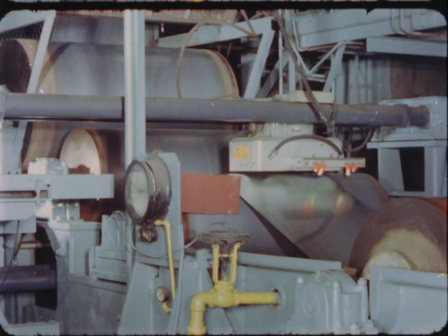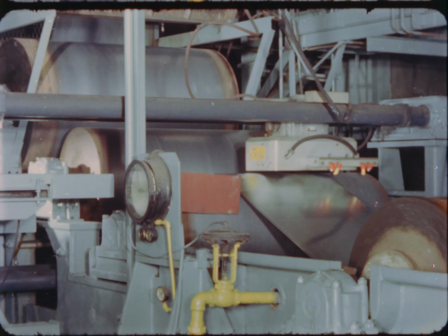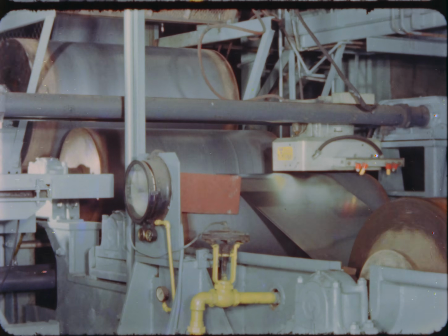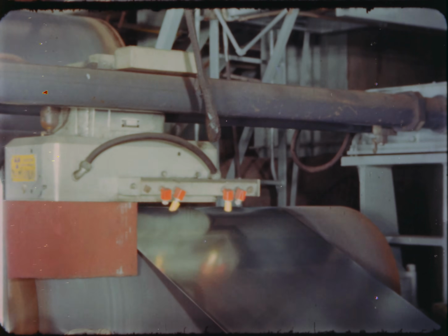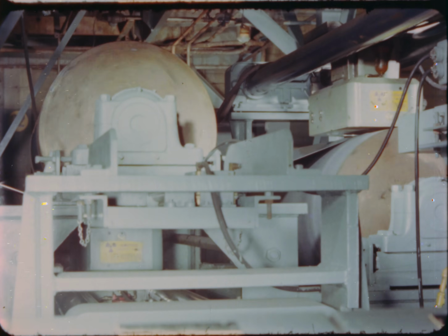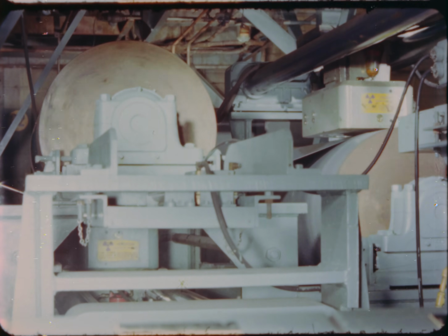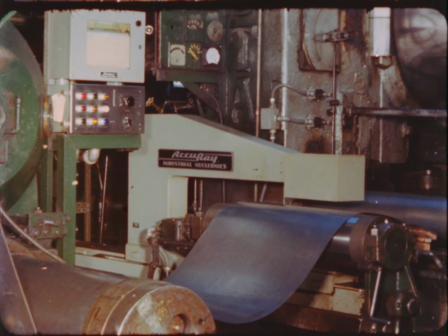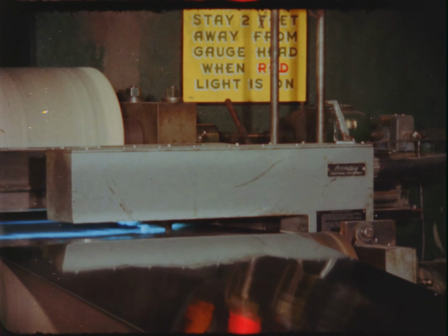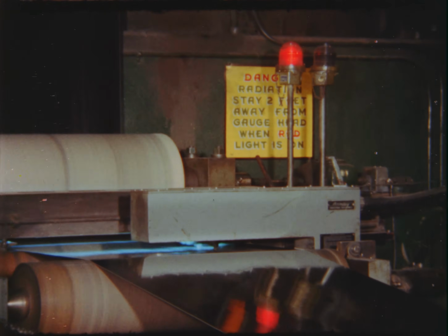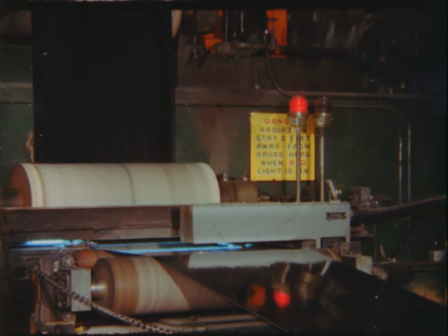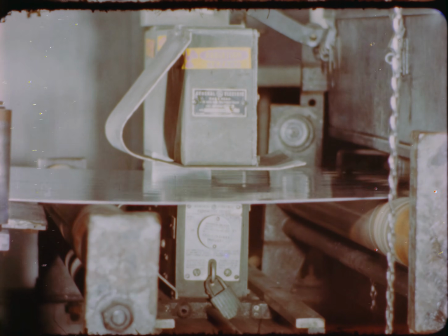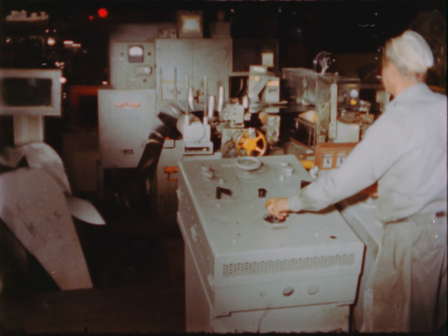Some important uses of radioisotope thickness gauges are evident in the steel industry, where they are employed for such processes as reduction of cold rolled strip, plating of tin on steel, galvanizing, and sheet classifying. In each case, the thickness and type of material being worked with dictates the type of gauge used and the strength of its radioactive source. A gamma gauge is necessary when the measurement and control of thick steel plate is required. A beta gauge is used in processes involving thin sheet metals or plating.